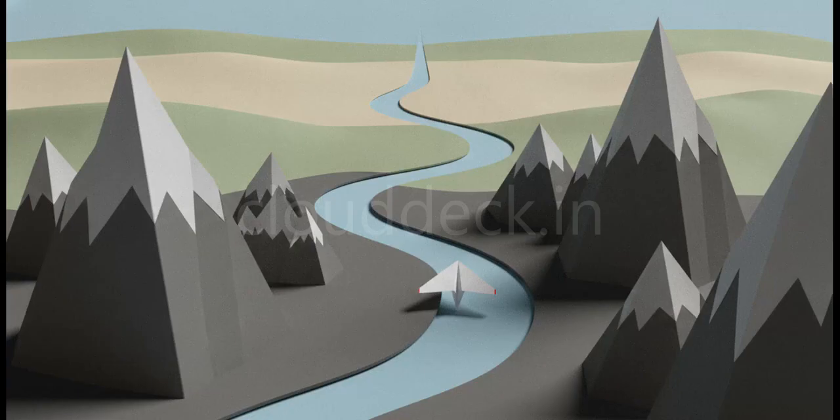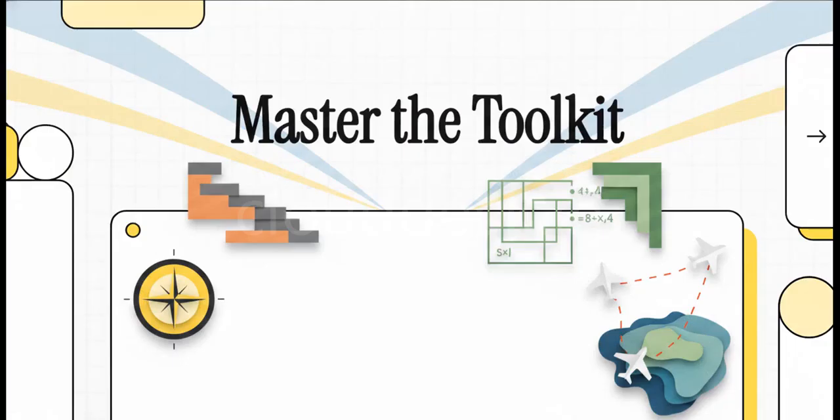And because of this continuous real-time self-monitoring, RNP allows aircraft to fly incredibly precise procedures. These are quantified by specific values. An RNP value simply represents the lateral accuracy in nautical miles that the aircraft must achieve 95% of the flight time. For example, RNP 2 is typically used for wide en route flying, meaning the aircraft stays within 2 nautical miles of the centerline. But for really tight, curved instrument approaches through, say, mountainous terrain, we rely on a highly precise RNP 0.1, which keeps the aircraft locked within 1/10 of a nautical mile. That's incredible precision.